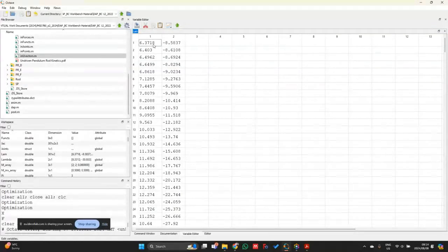The reason why I get a different sign over here is simply due to Newton's third law on the reaction forces. So I perhaps calculated it originally on the pendulum rod, where this system then calculates it on the grounded revolute joint. But the sign itself doesn't really matter as long as the magnitude is correct to some extent. Yes, that's correct. So the fact that I get the correct magnitudes over here gives me confidence that this is actually the correct problem that I want to solve.